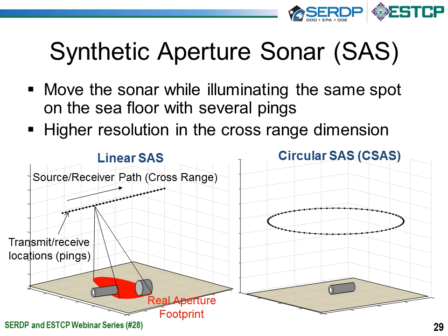And furthermore, we can get spectral features. When we think of SAS, we also tend to think of systems that have a wide range of bandwidth. So high frequency in a synthetic aperture sonar context typically refers to the low hundreds of kilohertz. So if you're thinking about, say, a side scan system, very high frequency side scan systems may be over megahertz. For high frequency systems, you tend to be operating at maybe 150 kilohertz. There are some systems that go even above 300 kilohertz, but those are very high frequencies for a synthetic aperture system. On the low end, we tend to see things in the low tens of kilohertz.